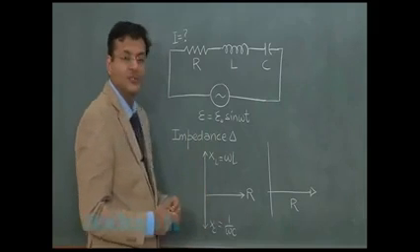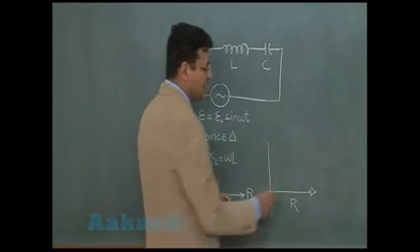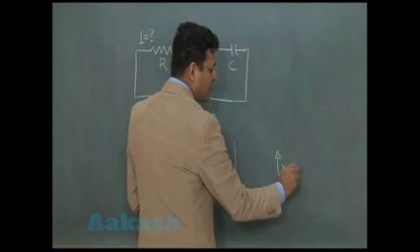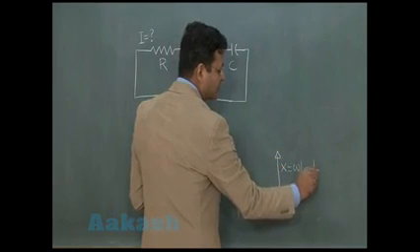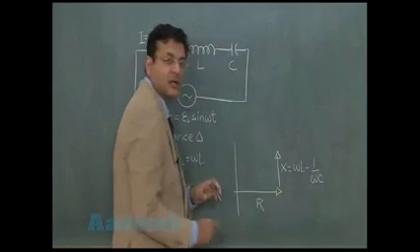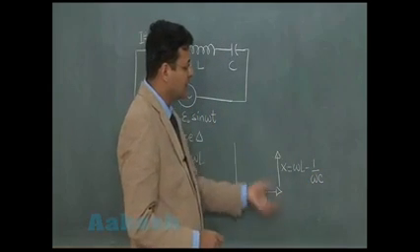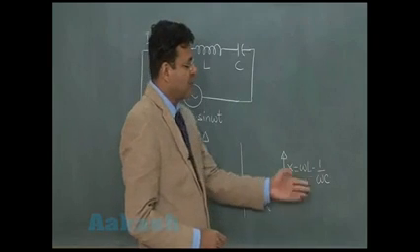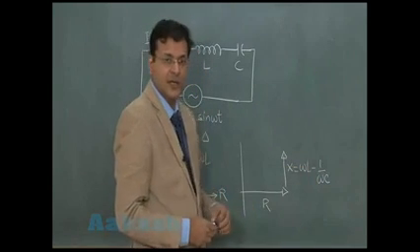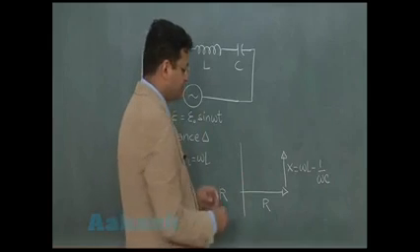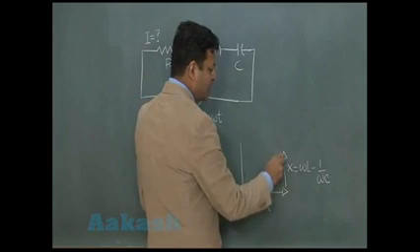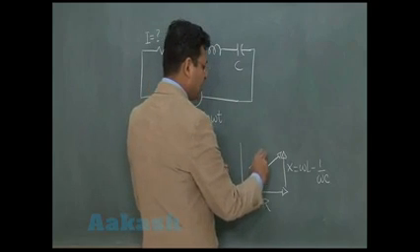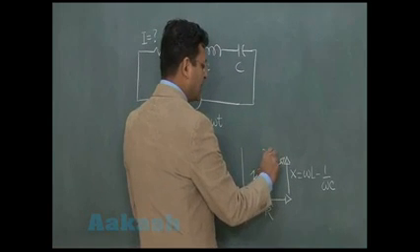Since both of them are in opposite direction, the net reactance of the circuit I may be allowed to plot like X is equal to omega L minus 1 by omega C. अगर capacitor dominant होता, then X must have been plotted on the other side, and the value must have been 1 by omega C minus 1 by omega L. Does not make any difference. You can say that the net Z value is essentially the Pythagoras of R and X.